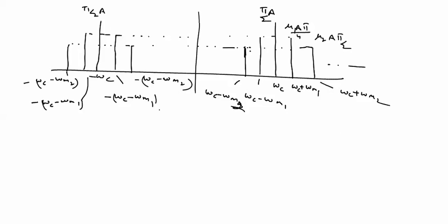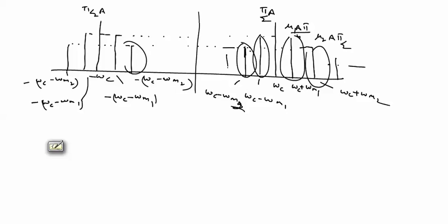We segregate all the terms. If we add two terms for transmission, this adds one upper sideband and one lower sideband. If we add one more frequency, we get an upper sideband and lower sideband, the same on the negative side also. If we add one more frequency, again an upper and lower sideband, this spectrum is spread in a frequency band. So the bandwidth for this we can calculate